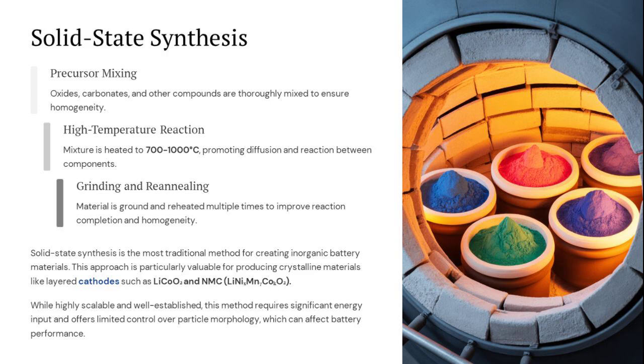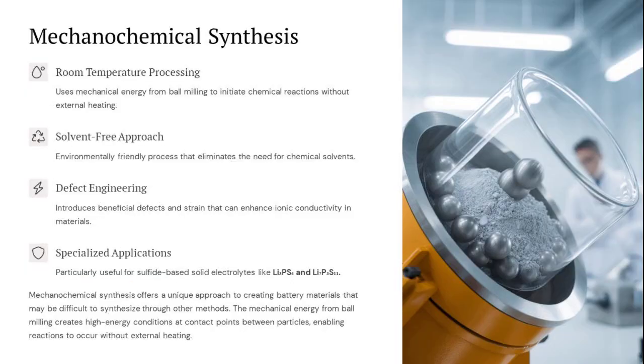For instance, research has demonstrated that Sr2+ and Ta5+ co-doped Li0.5La0.5-xSrxTi1-xTaxO3 perovskites synthesized by solid-state reaction showed significantly improved ionic conductivity compared to undoped specimens. The co-doping approach used larger ionic radius elements to increase the bottleneck size of migration pathways, thereby enhancing lithium-ion mobility through the structure.